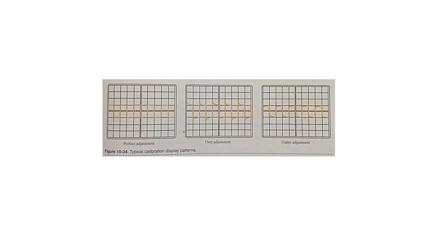See figure 10-34. Three examples of the square wave are shown. The rounded off or sharp peaked corners of the square wave patterns indicate that the probe needs adjustment. There's usually a small screw head in the side of the probe or at the connector. Adjust the screw until the square wave has a nice squared off corner appearance, as indicated in the frame on the left side of figure 10-34.